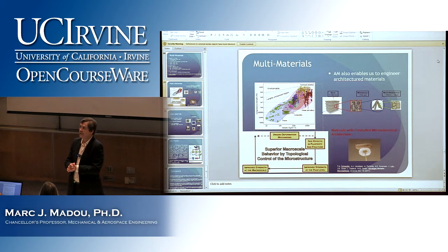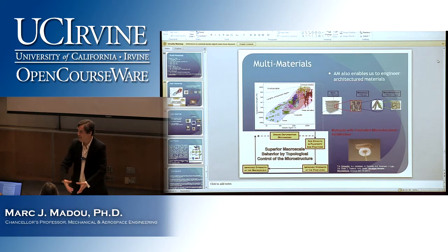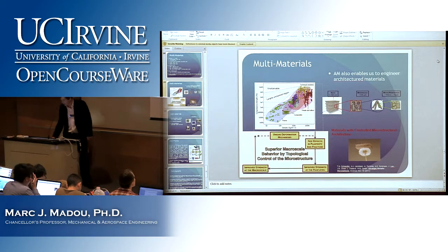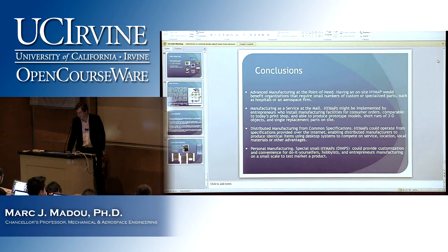And with additive manufacturing, let's say you're going to do a polymer and it's a rather heavy, dense polymer. Well, what you can do is you can make the middle hollow, or you can make it structural with big cells, big holes. And then as you go outside, you can make the holes smaller and smaller. Imagine how would you manufacture that ever, right? So that's a very important new trend, I think, that could really catapult this additive manufacturing to prominence very quickly. Good?